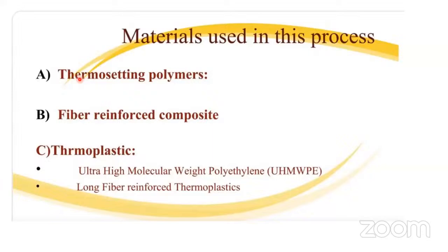A-stage resin means a completely pure novolac resin or phenol formaldehyde resin, pure, without adding anything. Just the reaction of phenol plus formaldehyde. You are getting the product of phenol formaldehyde, maybe a novolac resin. It is in powder form. This resin is called an A-stage resin.